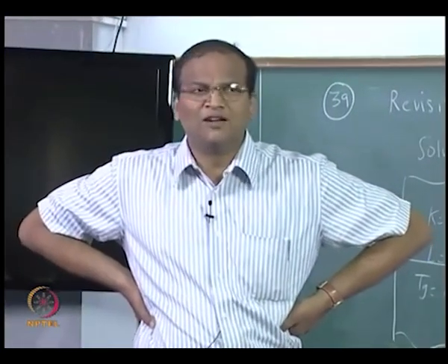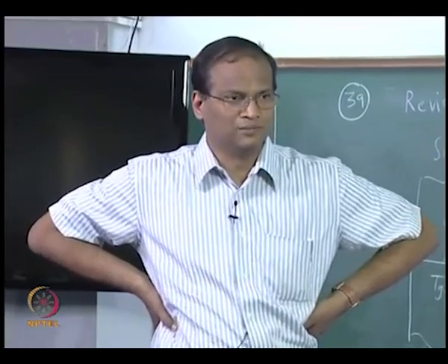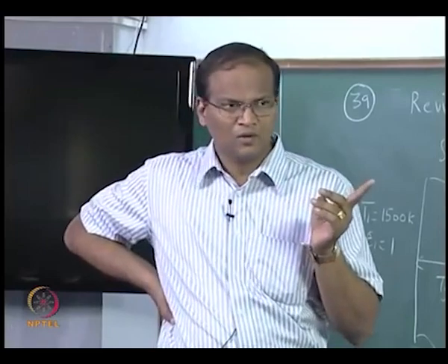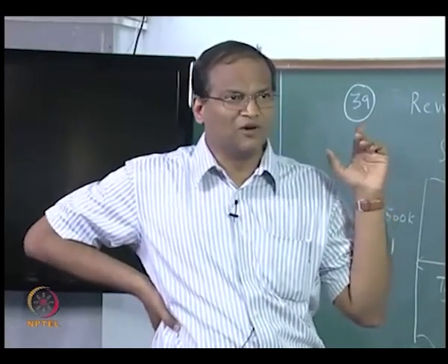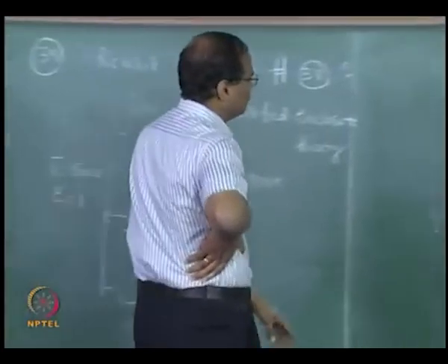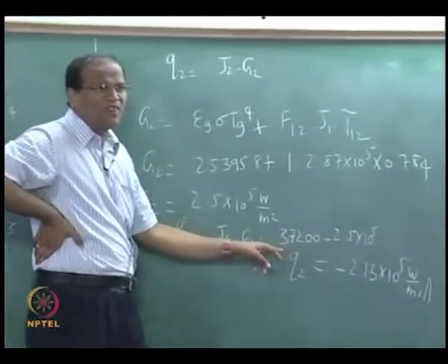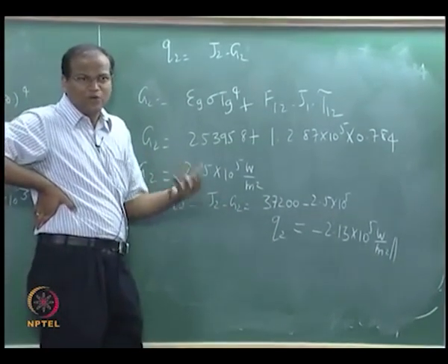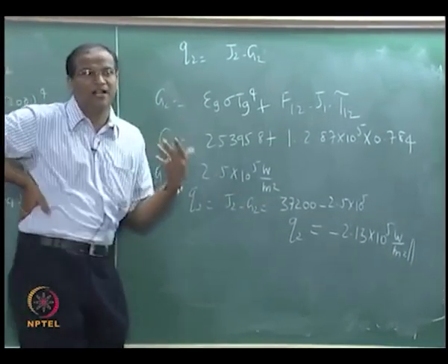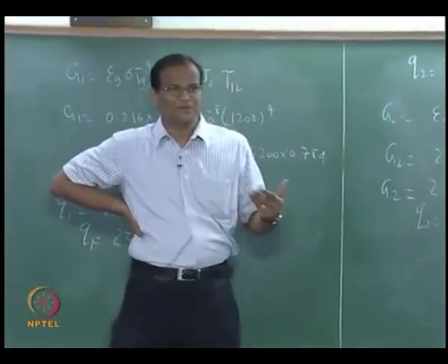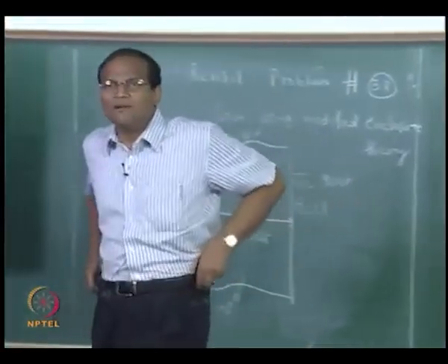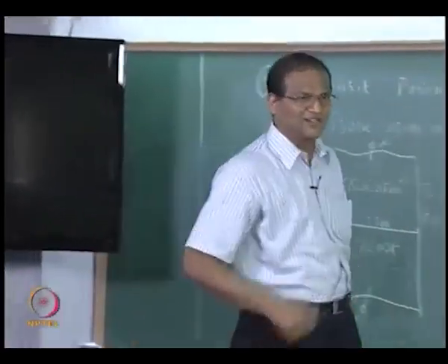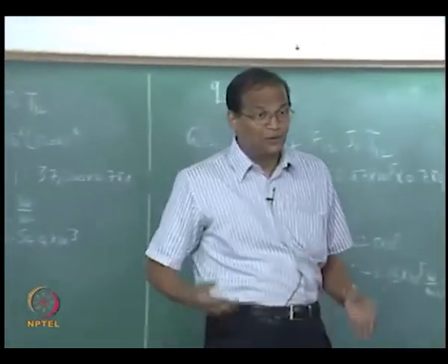So, a solution to a radiative transfer equation does not guarantee equilibrium. So, the gas is getting heated, is it? Is that correct what we got? Because 235 is coming out from the left wall, 232 is coming out from the left wall, but this fellow is able to absorb only 213 kilowatt. So, 19 kilowatts every second, 19 kilojoules per second of energy is being absorbed by the gas. The gas has to get heated up. So, my equilibrium temperature should be above or below 1200? It should be above 1200. Just see whether you are getting it. I hope so. Okay.